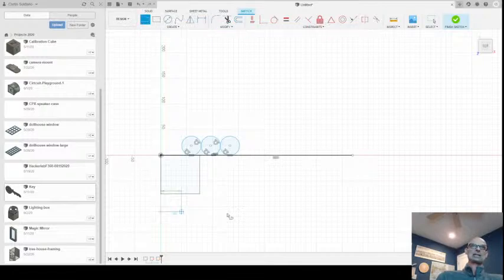And I'm going to create that line here and here. I don't know if you notice this, when I'm creating lines, Fusion 360 has UI that once I click the second point, I can end it by just passing over this little green confirmation button. That'll end the line creation phase, if you will, and I can start to tweak it. You'll also notice that there's a degree, an angle, and a measurement associated with these.